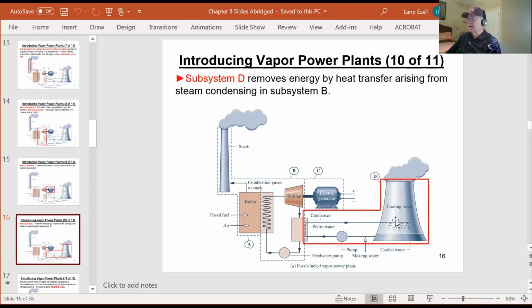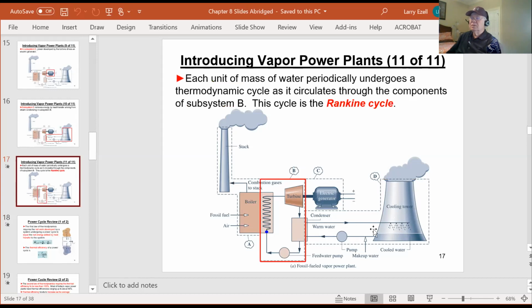We had 3 circulating pumps, each one of them, I think, about 100 horsepower, and we converted them to variable speed. We saved a lot of electrical energy in this system. Okay.